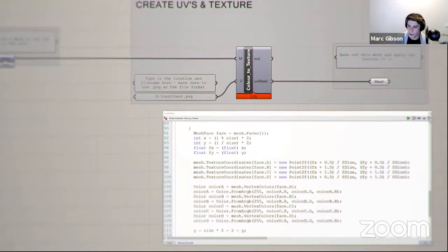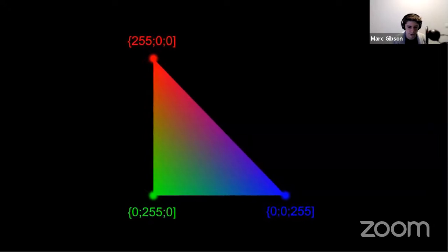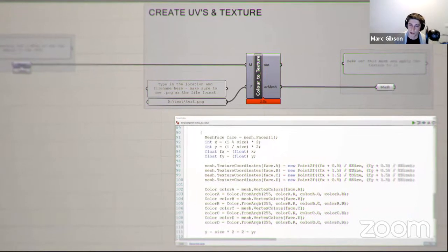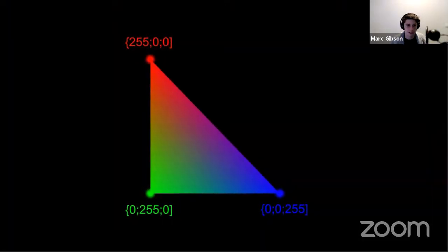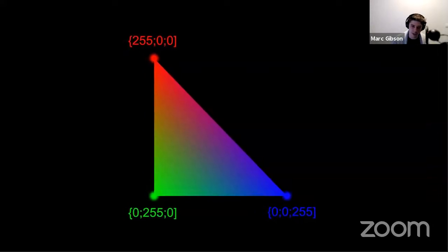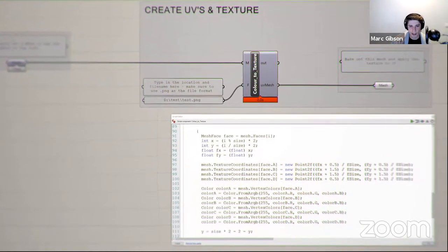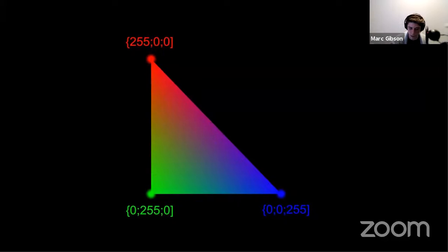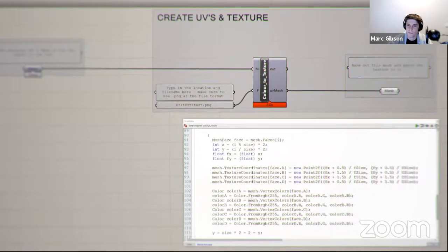So the first process is really post-process to the formation of the object, and that's looking at something called a trivial per triangle unwrap. And it's a fairly simplistic approach where basically you unweld the geometry, unweld the mesh, and you translate the vertex color information from each point to a pixel on a texture, a flat 2D texture.